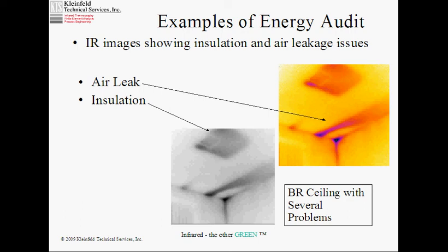There are two issues here. One is the air streak coming in from the cornice or the eave. The shape of it tells you it's air. The other is the ceiling light. Many ceiling lights, less so now than previously, required no contact between the light in the ceiling and the insulation.